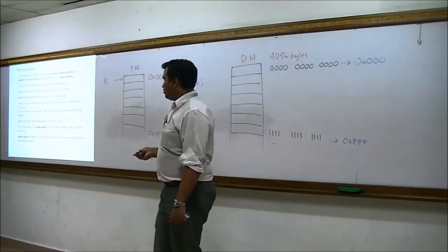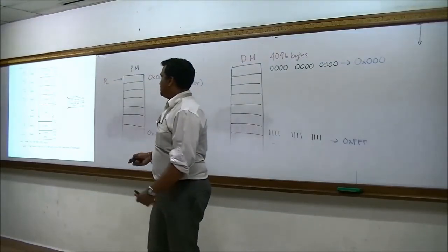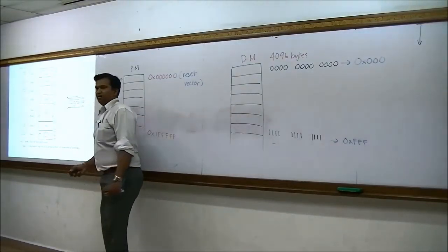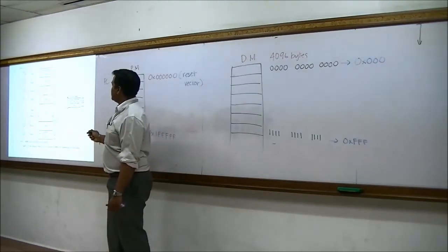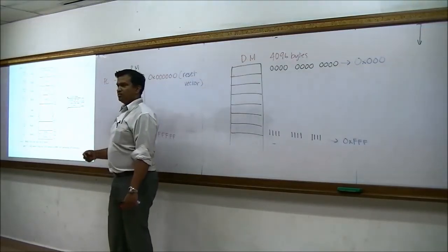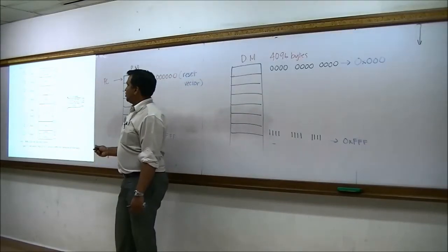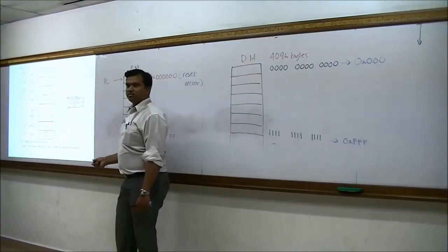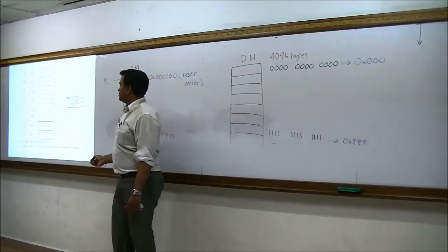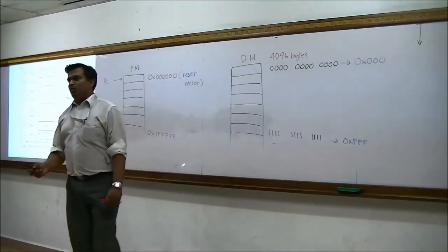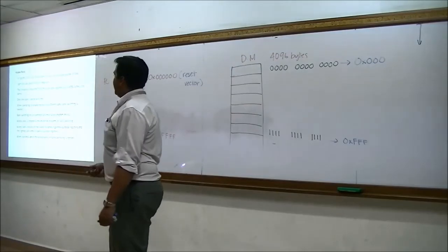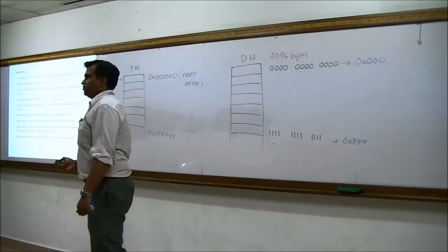So for now, how do we see this? This is your data memory. Do you see that from here to here is all GPR? Only the bottom one is SFR. You can see the address range is 000 to maximum FFF. Of course, you may ask what is this line and all these things. We'll come back to that later. All this is GPR, and this is SFR, the special function registers. You cannot simply load any values here, as it will change the behavior of the CPU. But for the GPR, yes, you can load whatever you want. Is this okay up to this point? We shall move on. The access bank we'll skip for now because you won't understand it yet.